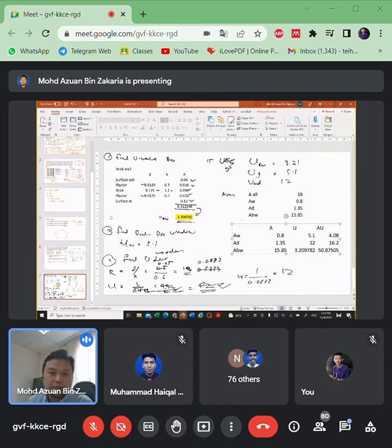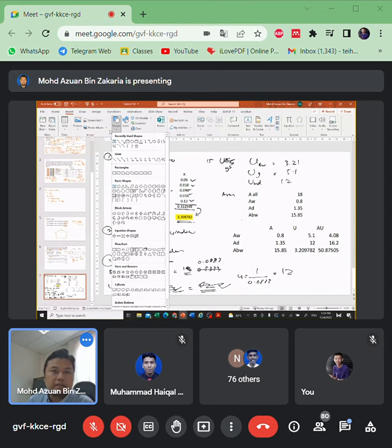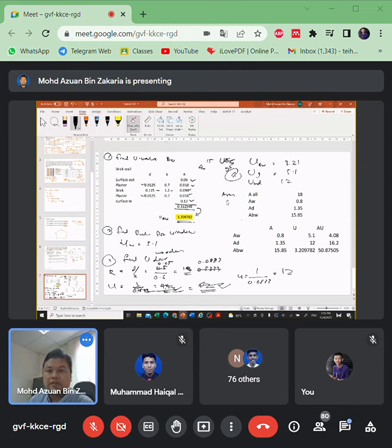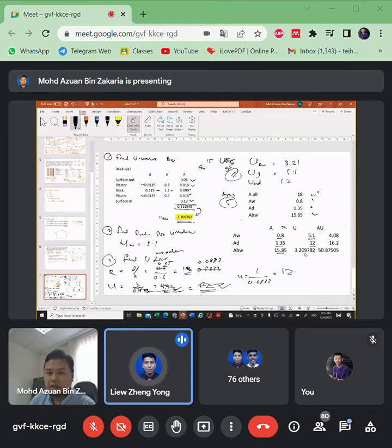So I can say 1, 2, 3. Step 4, we list it again. Step 5, calculate area, and then A times U. So A window multiply U window, door multiply U door. Sorry, doctor. I think the area for door is 1.53.